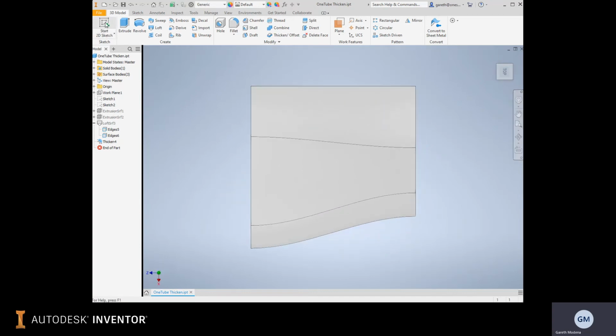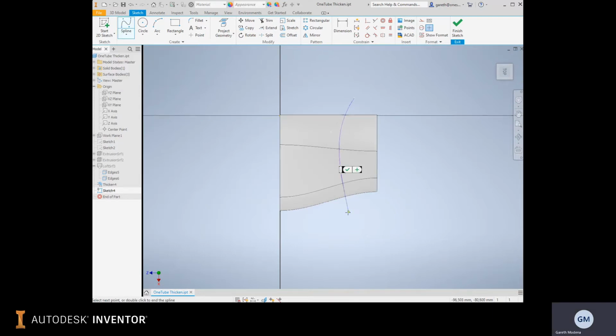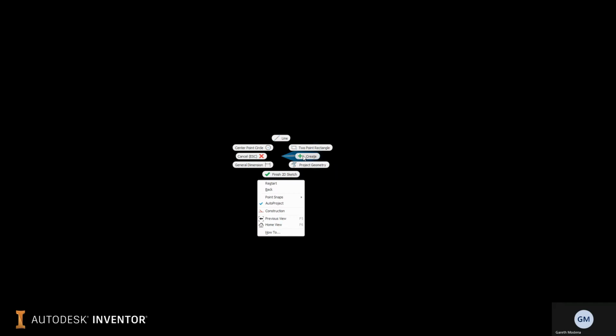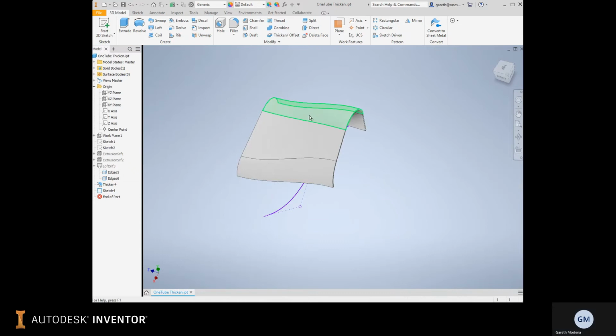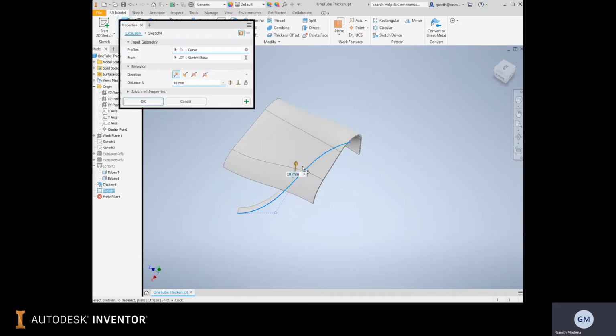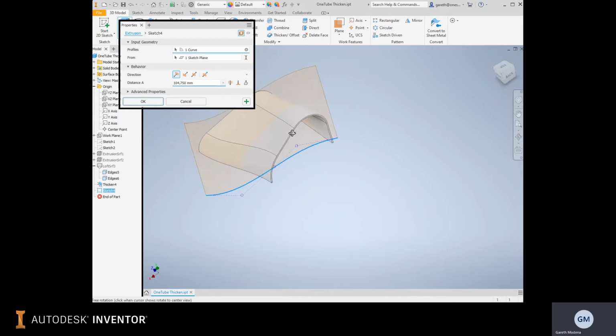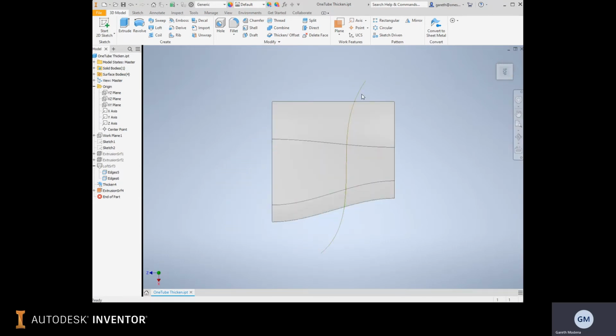So in this case, I'm going to create a sketch in plan view on our origin X Z plane. And what I'm going to do is create a spline between a couple of bodies. Create that. And that's going to represent our split tool. So if we go to creating an extrude out of that, it's automatically going to be a surface because it's actually just infinitely thin, and it'll accept that. So I want to cut our housing at this curve of this item.